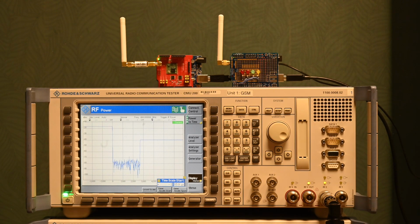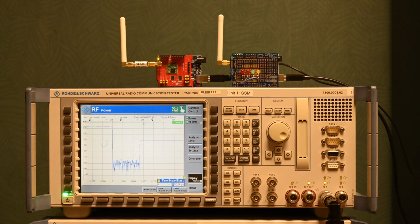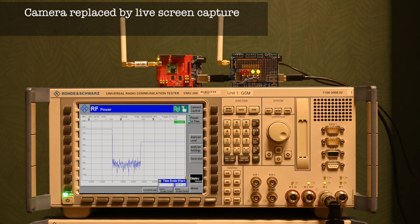So you can see it's still triggering. And so what we see here is actually the last part of the burst of the sending signal. We see the short delay before this unit reacts, and then we see the reaction of the other unit. And now we can perfectly see basically the levels, which is about minus 20 dB for the transmitter, and it's about minus 40 dBm. I always say dB, but it's dBm of course here, relative to power, for the other unit basically.